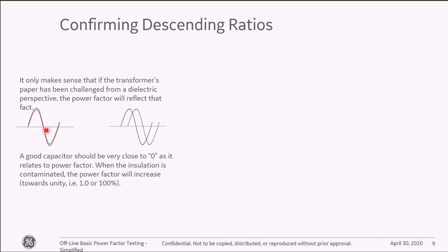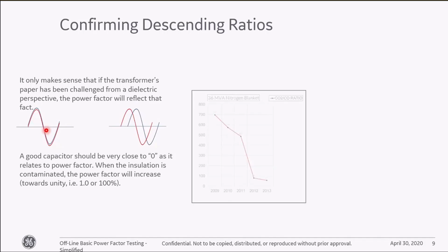So you really want your current and voltage out of phase by 90 degrees, as opposed to in phase across the capacitor. So when you think about a bushing, the ground flange, the tank is one conductor, right? Because the tank is grounded, and earth is a conductor. So you have your incoming conductor to your bushing. Your cable or your buswork connects up to your bushing. So that connection remains all the way through, and along the way, you have this insulation so that the power has a highway to get through there. Okay.